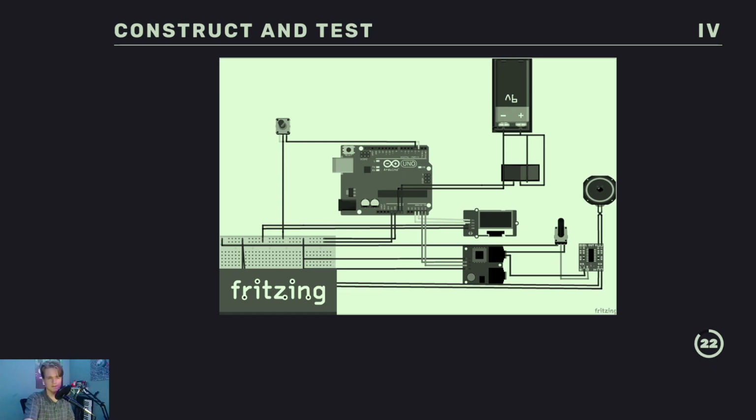Basically, the way it works is you have a 9-volt battery input, or actually 6-volt, but the 9-volt was the best I could find in this program. It goes to a power switch, and then a rotary encoder is hooked up to the Arduino. Whenever it updated the radio, it would send the signal to the radio and the display. Then from the radio, the left and right channels would go through a potentiometer, which would increase the signal strength, and then through an amplifier to really increase the signal strength. So the potentiometer actually worked as a volume knob, and then that would go out to the speaker. Very cool system, and I learned a lot in this process.